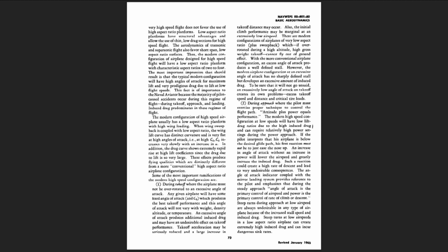The most important impression that should result is that the typical modern configuration will have high angles of attack for maximum lift and very prodigious drag due to lift at low flight speeds. This fact is of importance to the naval aviator because the majority of pilot-caused accidents occur during this regime of flight: during takeoff, approach, and landing. Induced drag predominates in these regimes of flight. The modern configuration of high-speed airplane usually has a low aspect ratio planform with high wing loading.